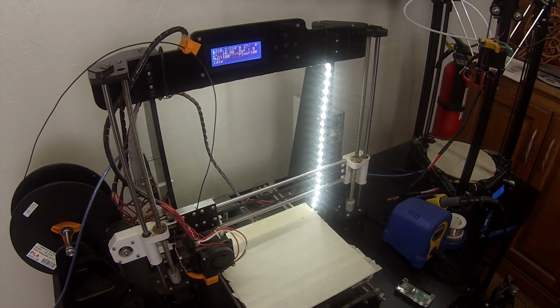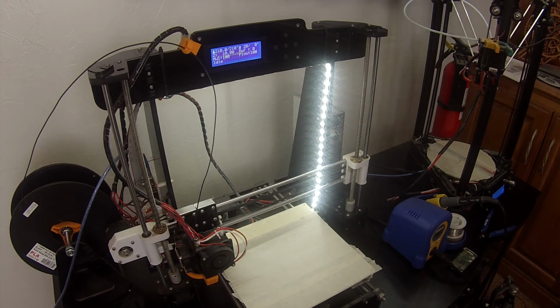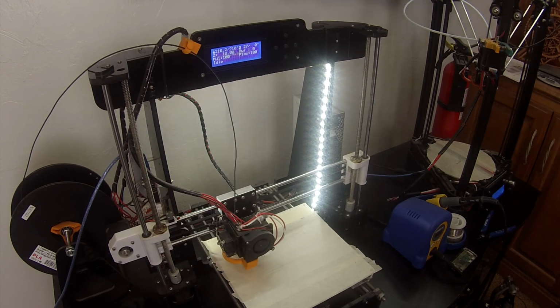On the subject of bed leveling, this is important for getting a high quality print. You need to make sure that as the print head moves across the bed, it doesn't matter if the printer is level on earth, it doesn't matter if your table is level relative to the printer. The only thing that matters is as this printer head traverses left and right across the bed, forward and back, that the bed is equidistant from that nozzle in as wide of a range as you can get, to as accurate of an extent as you can get.